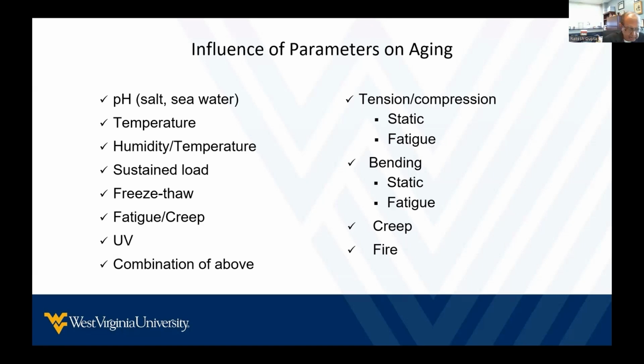In addition to this physical change, moisture can hydrolyze ester bonds within the matrix, particularly if you are using a polyester or a vinyl ester as the matrix, and this weakens the matrix. And this is made worse by addition of stress or an increase in temperature. The fibers can also be hurt by moisture ingress. We can have leaching of sodium or potassium oxide from the fibers. There are micro cracks, and ultimately the fiber can dissolve. And then it obviously loses its ability to bear a load.